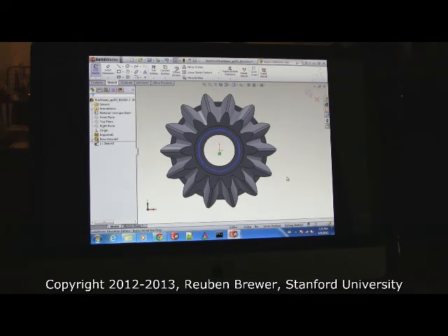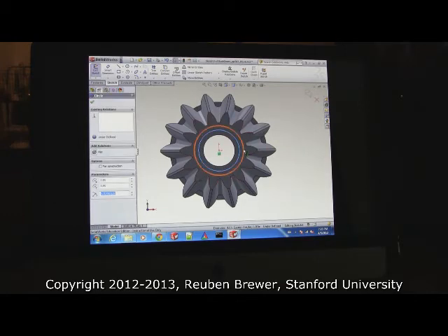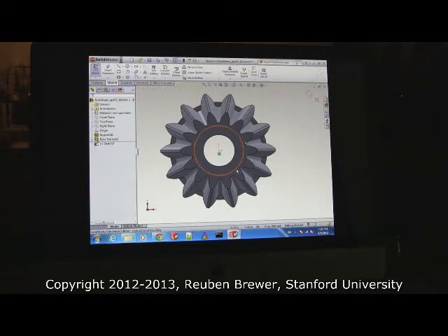Now, I could measure the diameter and then dimension it to that diameter. What's the problem with doing that? If I ever change the other thing, I have to change everything. So what we're going to do is make it do it automatically. Click the circle, hit Control, click the bigger circle right next to it. Now in the left-hand corner, see on my screen, co-radial. Co-radial means they're going to be identical radii. Click that. Now I have a black circle, fully constrained. Perfect.